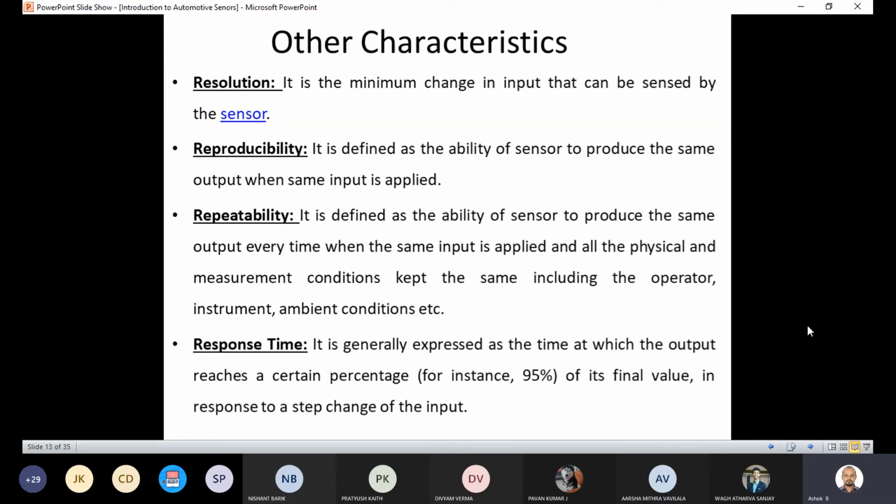If you take the exhaust gas oxygen sensor, and today it is giving one output and tomorrow it is giving another, then ultimately it will affect the air fuel ratio of the vehicle, and it will have a negative impact on the fuel economy. So the important aspect is that the reproducibility and repeatability of the sensor have to be very appropriate in the entire operating span, both with the presence of disturbance and without disturbance.